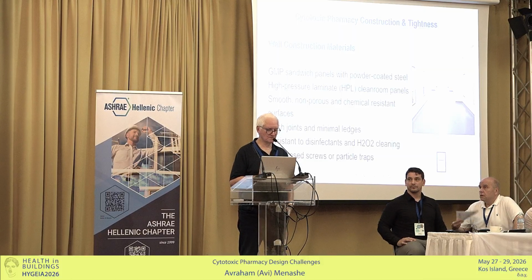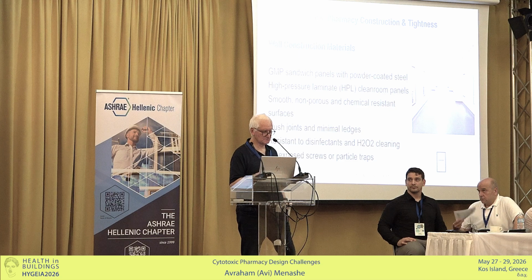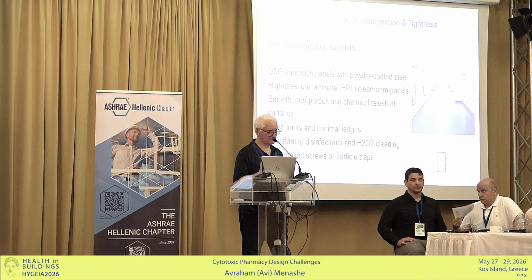They must be very smooth in order to avoid any contamination on the wall. All the sockets and all the light fixtures should be suitable for clean rooms. We don't allow sharp edges; we need round edges to avoid any contamination and collection of particles.